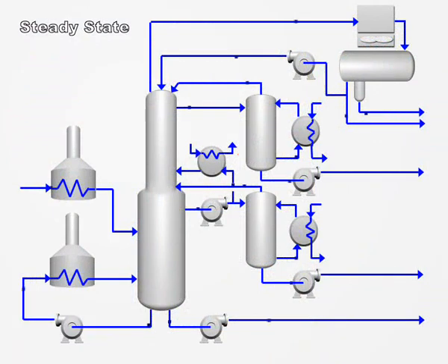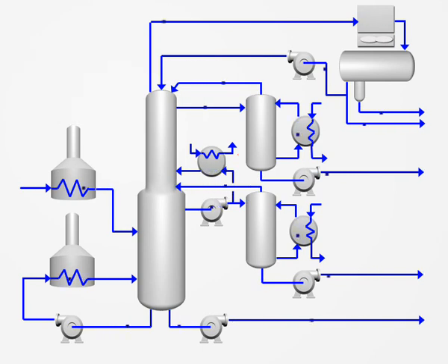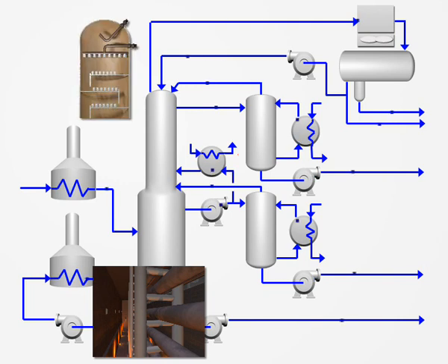The distillation system, with all its supporting equipment, will operate in a steady state. Increasing or decreasing operational parameters of one component will have an effect on the rest of the system. We've discussed several situations where, if we operate outside the proper limits, internals are being damaged. Operating within the appropriate boundaries gives the operator control over the efficiency of the system and the quality of the end products. We also discussed the effect of reboiler operation on the separation process and the results of adding reflux.